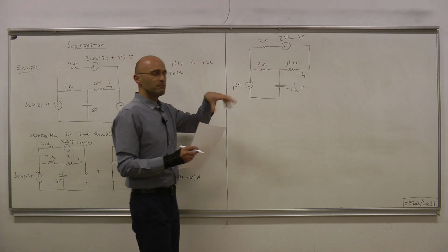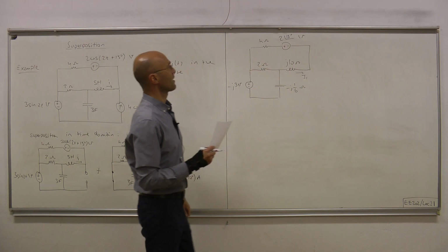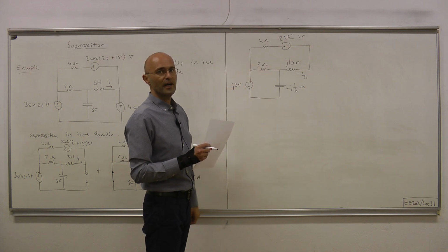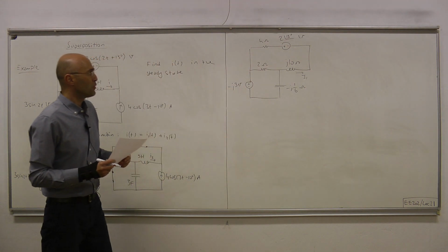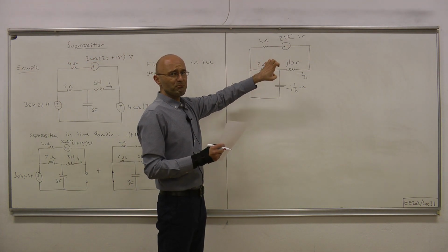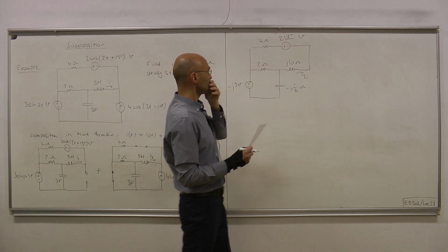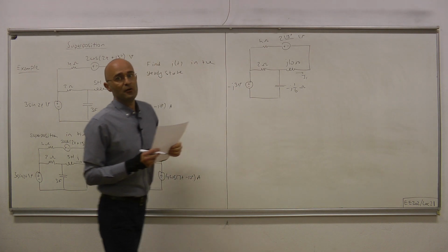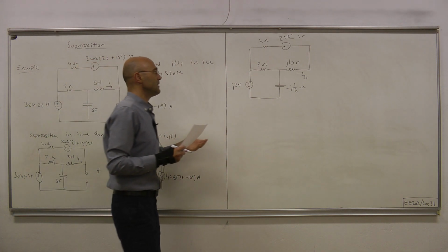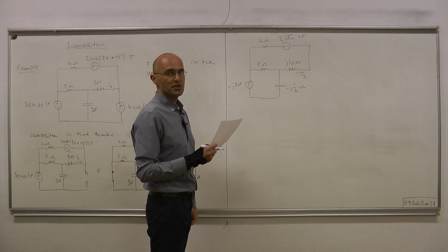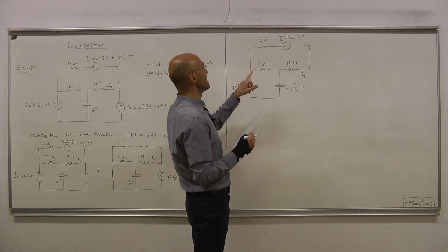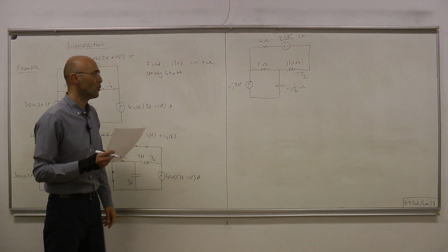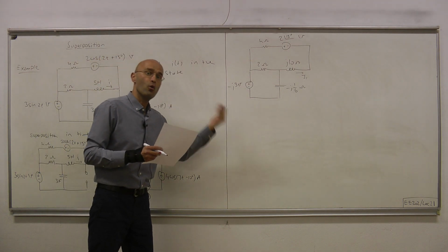Now, let's consider this phasor domain circuit, which has 2 inputs. Since it has 2 inputs, and since we've been saying that this is just like an LTI resistive circuit, clearly we can apply superposition and consider only one input at a time for this phasor domain circuit. In other words, we can apply superposition once again.